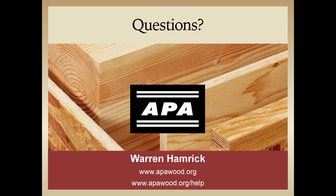Wonderful. I also had a question in here. I'm trying to group questions into like groups that mentioned that often studs are missed even with nailing even when studs are at 16. So moving them to 24, it sounds like as long as you have that wood structural panel, that may not be a concern.